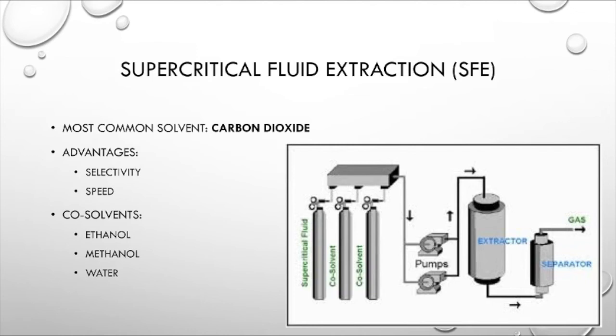The overall advantages of SFEs are the selectivity and speed improvements over regular extractions, which is due again to the differences in diffusivity properties. Typical co-solvents used in industry are ethanol, methanol, and water, which are used to enhance the solubility power of CO2, making it possible to extract much more polar molecules from a molecule of interest. The diagram here shows a typical process of an SFE.